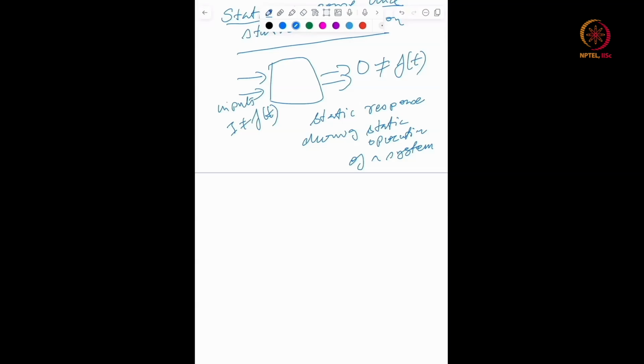Sometimes it is impossible or difficult to maintain all but one input constant, because changes in the desired input may trigger changes in other inputs as well. That means there is some sort of coupling between the inputs. In such cases, all changing inputs must be measured during calibration and different effects must be identified and separated.